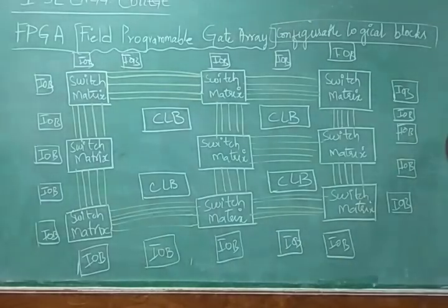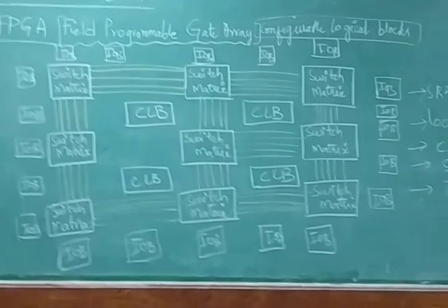We have seen it consists of SRAM, it has local and global configurable routes, that is nothing but routing. The next, the same thing, CLB consists of switch matrix, then it has input output blocks. So these are the things which you need to understand in order to get the concept of your FPGA, right?